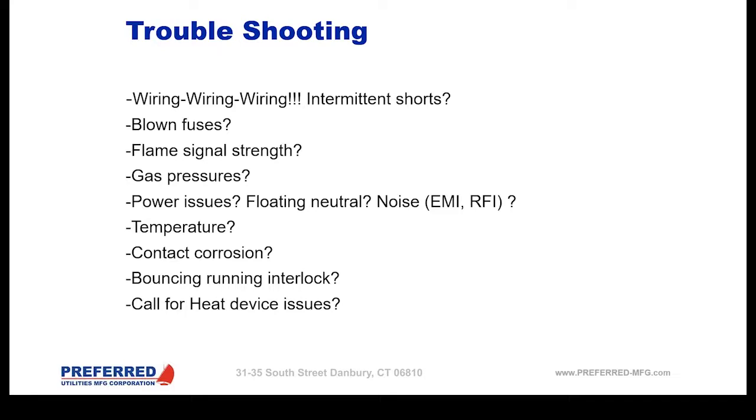So how do we prevent a lot of noise issues? Grounds. I can't stress enough. Proper grounding on everything that's required by the manuals on all the flame safeguards need to be done exactly like they're called for in the manuals. I check grounds immediately when there's any kind of issues, whether they're intermittent or consistent.